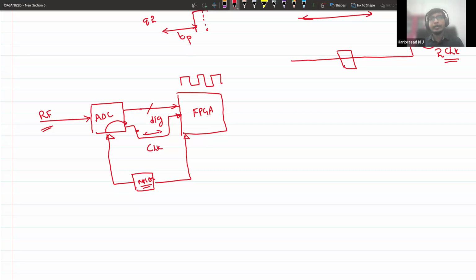It is not a low latency path here, mainly because these are on the PCB, whereas this is inside the FPGA, right? So these depend on trace length. Because of that, you're going to get some kind of skew in the clock. So how can we solve this kind of skew?